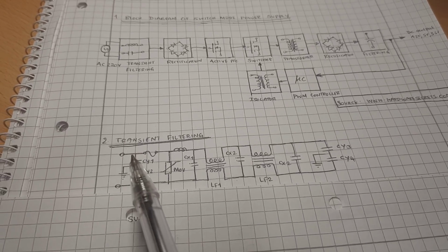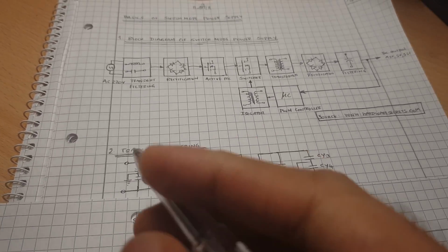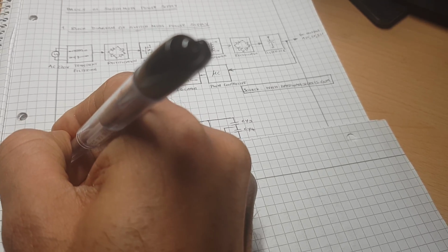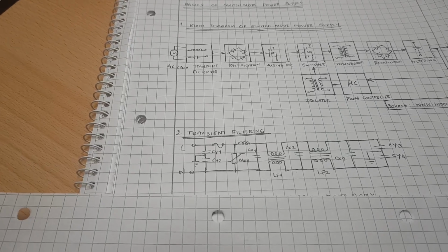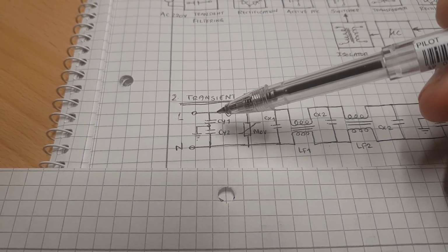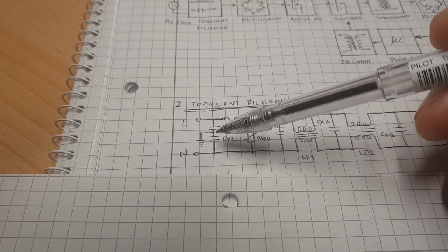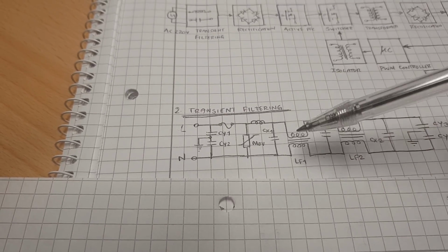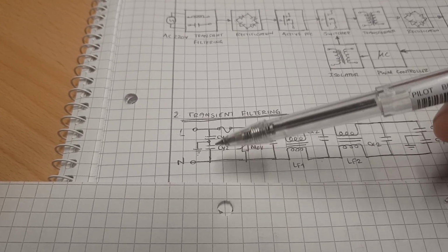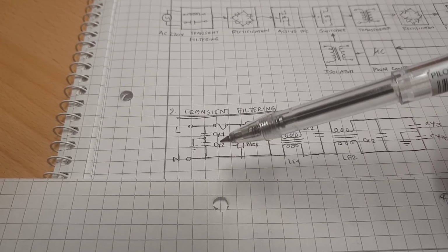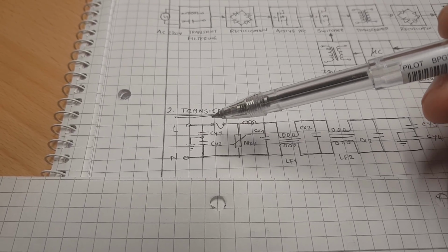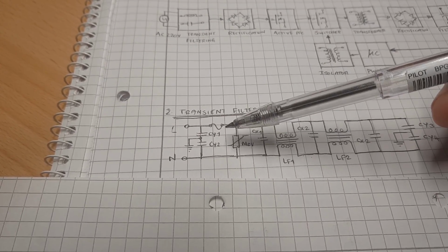The input comes from here. You have the live and neutral. So let me note it down. Live and neutral. So this is then connected to two capacitors in series, and the middle one is connected to the ground. Some of the power supplies do not have them, but depending on the power supply, you have this as well. The live is then connected to a fuse,